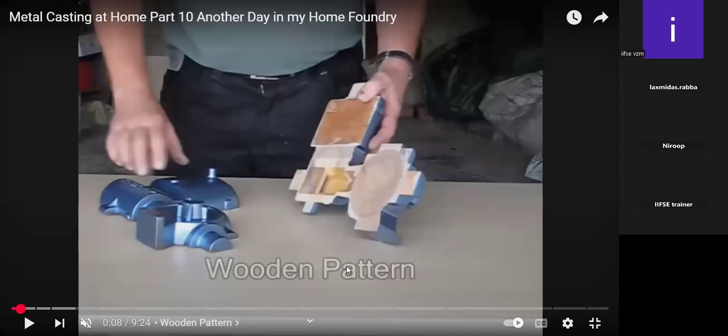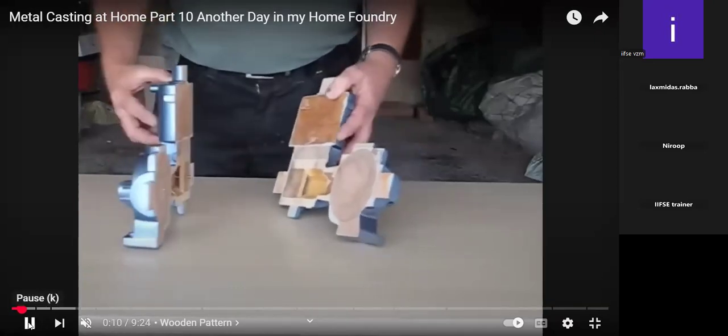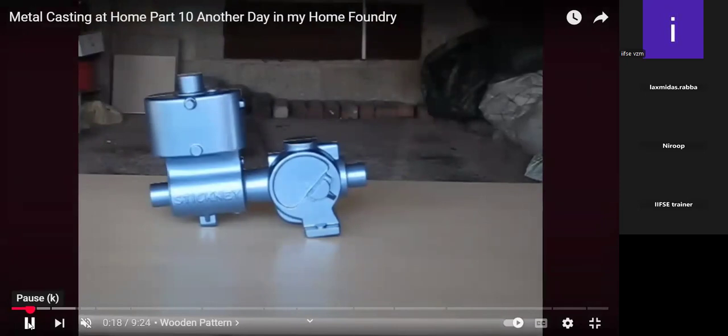Nowadays, they are also using 3D printers to make patterns instead of wood and aluminum, because wood and aluminum take so much time and so much skill to make patterns with precision and accurate quality. So nowadays they're using 3D printers for creating such patterns. If the two patterns come together, that is the desired part which we required.